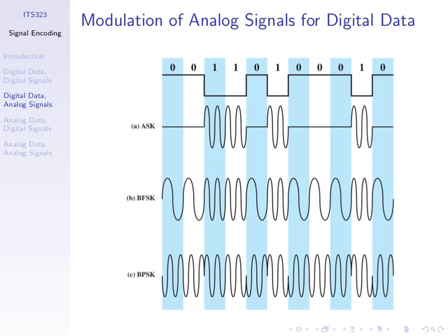So the receiver receives a signal. If the receiver receives this, it needs to, over this period, determine what is the frequency of this received signal. Okay, it's 1. That corresponds to a bit 0 being received. Here, the frequency is 2, or it's a higher frequency. Therefore, a bit 1 is received.